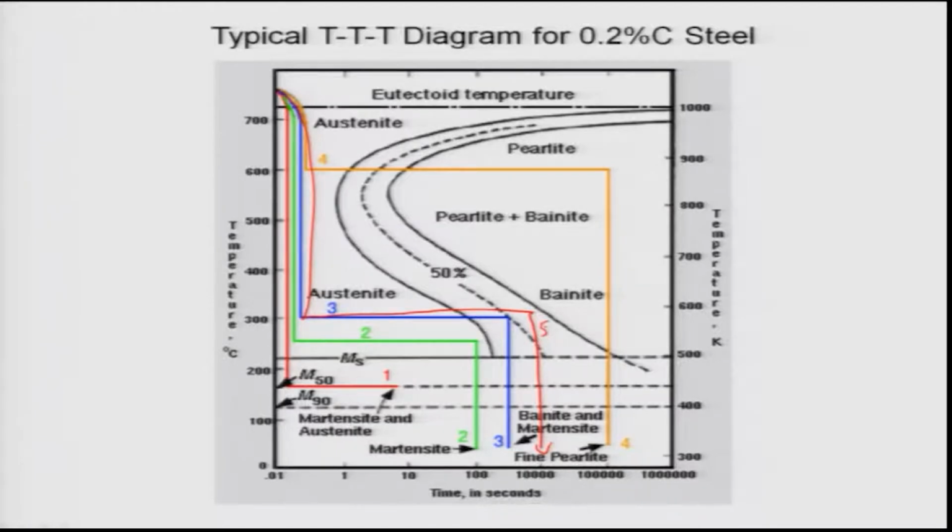And now you can actually do different kinds of bainite. You can cool it and do that, this will lead to upper bainite, or you can cool it and keep it at this and quench to water, giving upper bainite plus martensite, and 3 or 5 will lead to lower bainite plus martensite. The different kinds of morphology can be built into the microstructure.